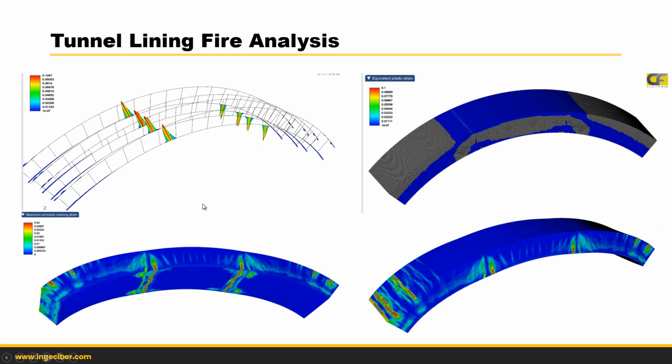We can see here some results that depend on the boundary conditions. We have the failure of the concrete, these cracks under the loads, where the positive bending moment is higher, and we have these cracks. Also, due to the negative bending moment at the supports, in case of completely constrained or flexible supports, we have these other cracks, and also some yielding of the steel at both supports and at these points.